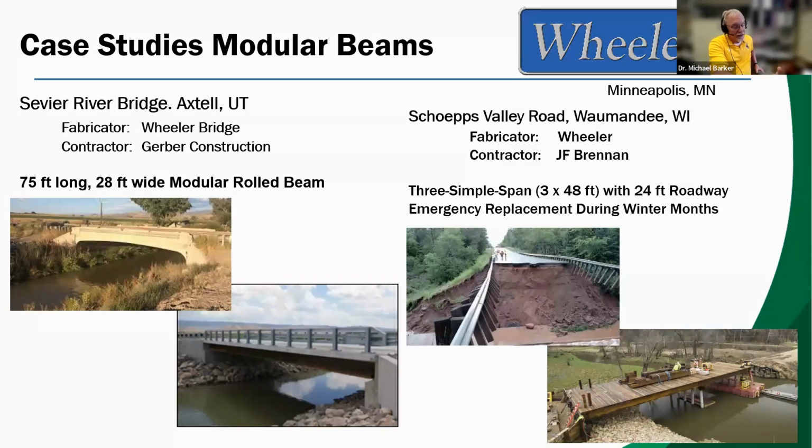And so Wheeler came in on that bottom right and said, hey, we can build a modular steel beam bridge with a wood deck, asphalt overlay, crash tested barriers, and steel and wood abutments. And we don't have to cast any concrete, and we can get this thing built really, really quickly. No concrete curing time, no concrete temperature issues. And so I just wanted to show these. Wheeler is in Minneapolis, and this is Minnesota LTAP, and the concrete and the wood deck systems.